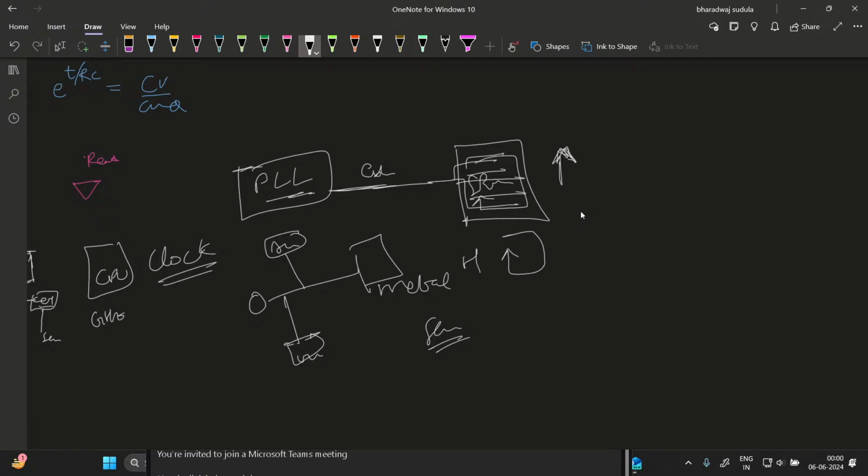That is the reason they have introduced this self timing, so that they can give a small area in that chip and just generate a clock, or pulses like sense enable, based on which block you want to run. You get a clock from a source, but it will automate that clock frequency based on what frequency that block wants.